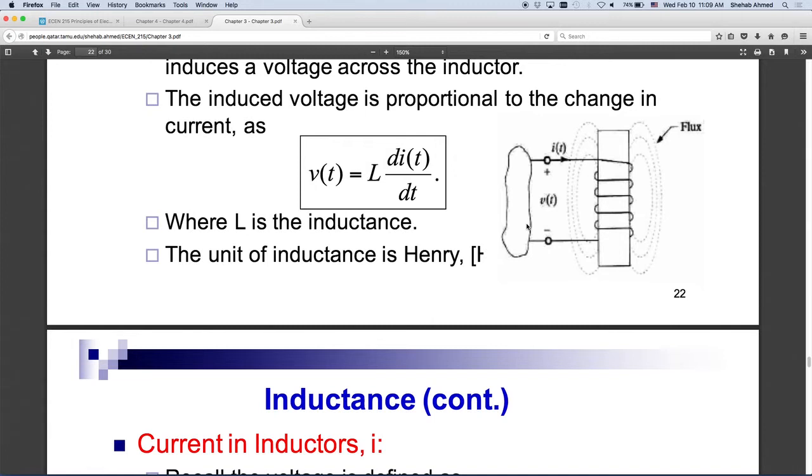So if you're not increasing flux, what are you doing? You're not really making an inductor anymore, you're just burning power. So same as the capacitor, it has a limit. The limit is the flux density of the material that you're winding this core around.